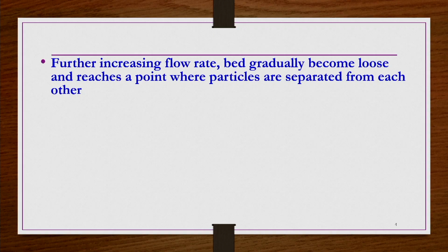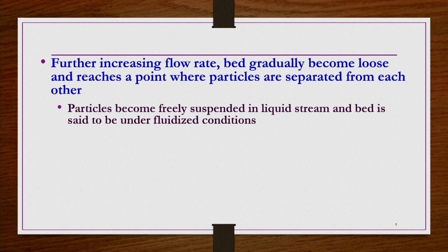Further increasing the flow rate, the bed gradually becomes loose and reaches a point where the particles are separated from each other, and then the particles become freely suspended in the liquid stream, and the bed is said to be under fluidized conditions. The same thing we are going to see pictorially in the next slide anyway.